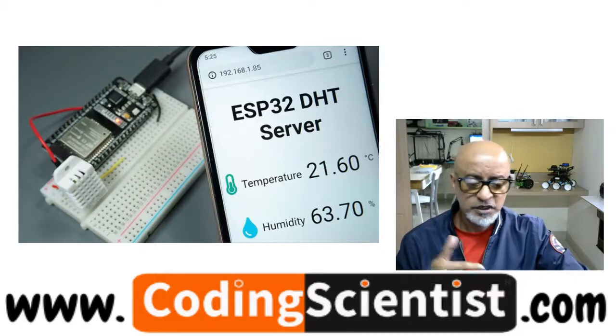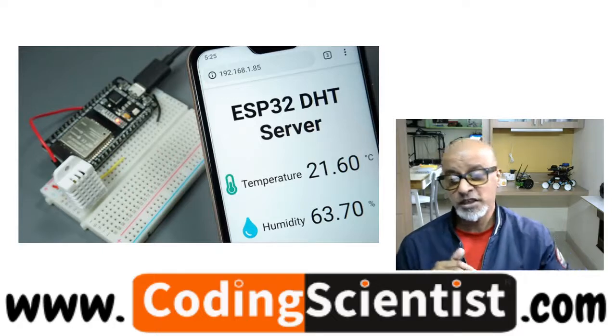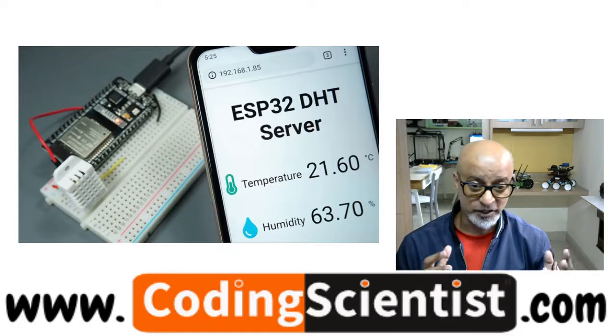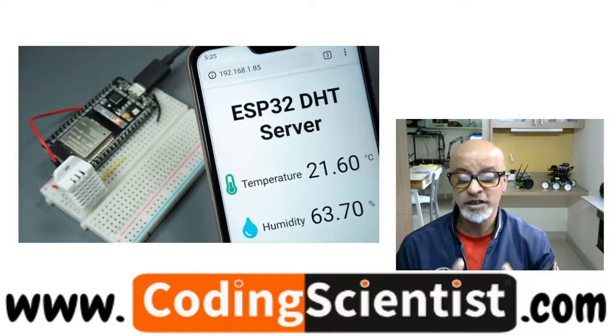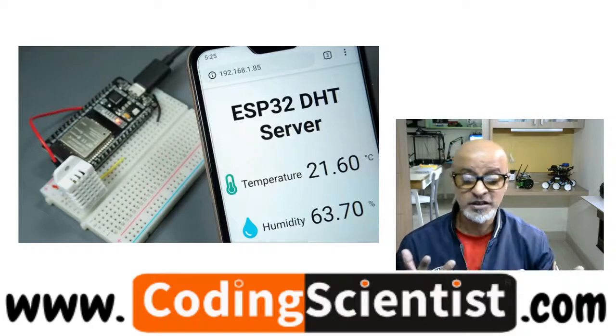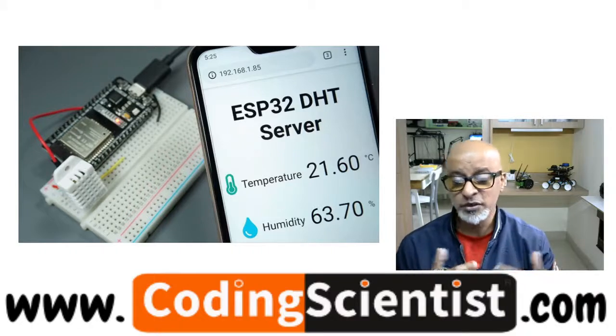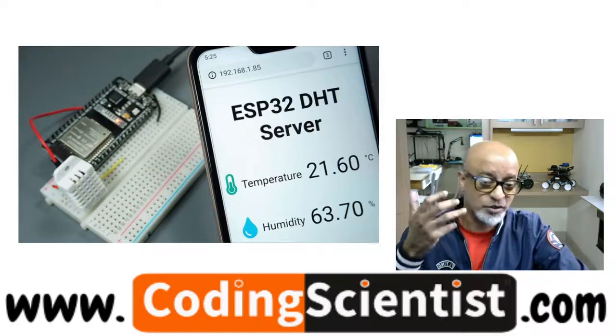As part of this lesson, you will also learn how to build an asynchronous web server using the ESPAsyncWebServer library, which is what we downloaded a couple of lessons back. In this lesson also we need the same library. And then you will also learn how to update the sensor reading automatically without the need to refresh the web page. It's a part of the C++ code, right?